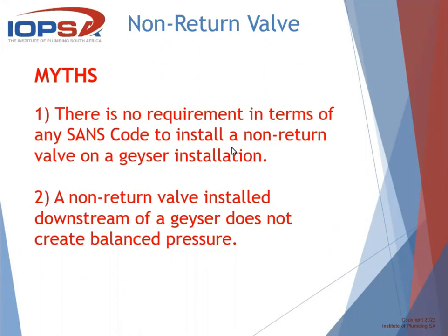And that doesn't, so the pump doesn't push enough water flow. So it tends to create this vibration, and the valve opens, then shuts, and opens and shuts very rapidly because there isn't enough flow. And in some cases, it actually stops the flow completely because the pump simply cannot overcome the pressure of the spring. And I've seen that a few times.